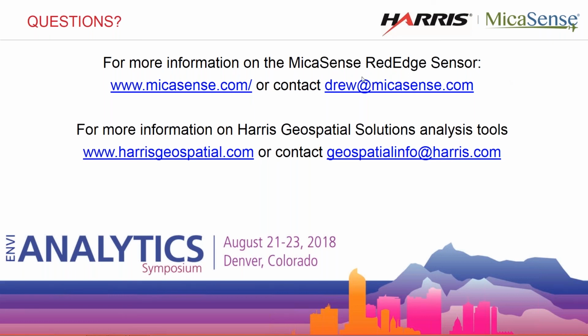That's great. What would be the best height to fly using MicaSense RedEdge? One for you, Drew. Most people fly at 400 feet, and the reason for doing that is just to limit the amount of data collected. That captures spatial resolution of about 8 centimeters per pixel, and for most uses, that's definitely good enough. So 400 feet is the maximum you can fly. That's typically what people fly.